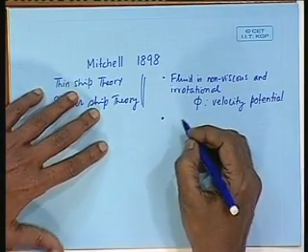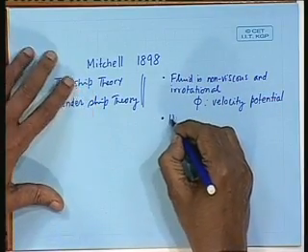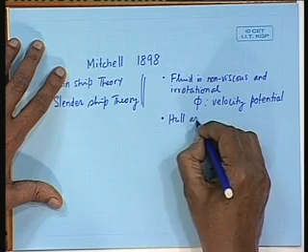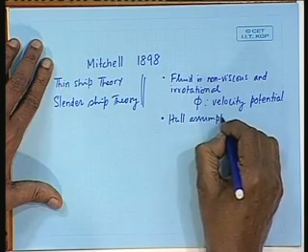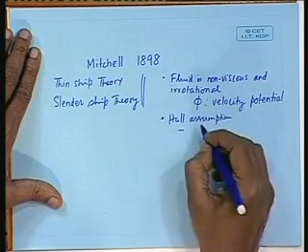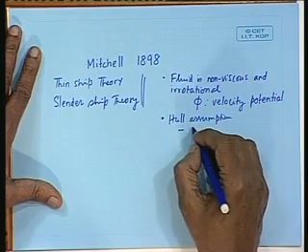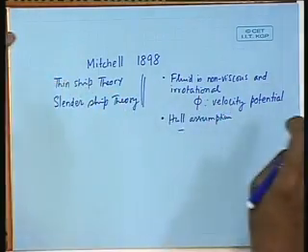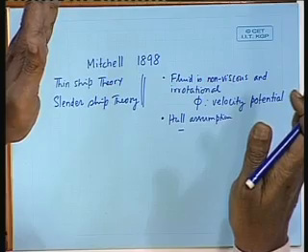What are the other assumptions? The hull assumption. In thin ship theory, we said that any breadth dimension of the ship is small compared to the length dimension. That is, the ship is thin.